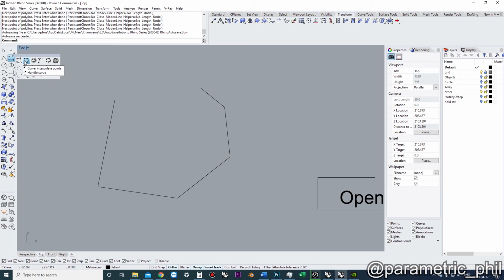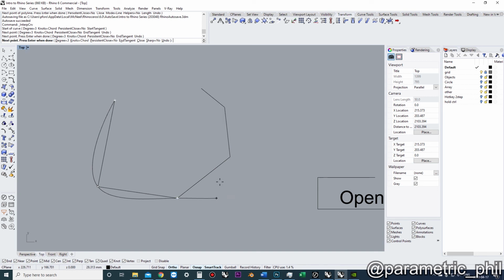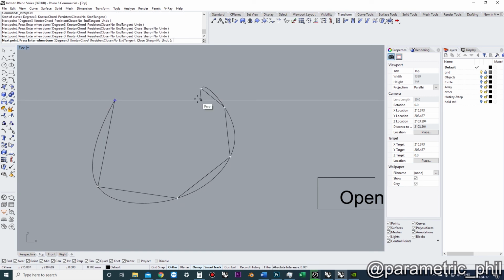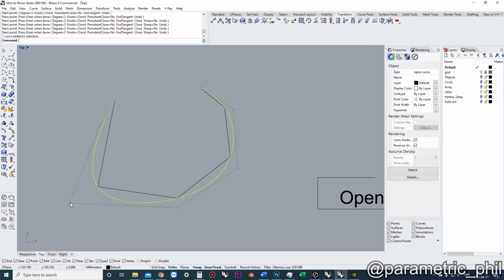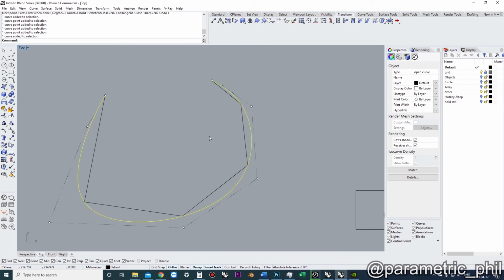And we can choose the Interpolate points curve. And what this is, it's different than the last one that we looked at, because this curve will always intersect the points that we draw. So now it's important to remember that this is still drawing a control points curve. See, it's actually drawn the control points, and the intersecting points, the interpolated points, those are just to construct it.